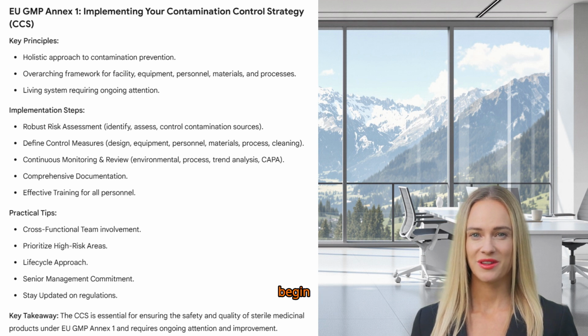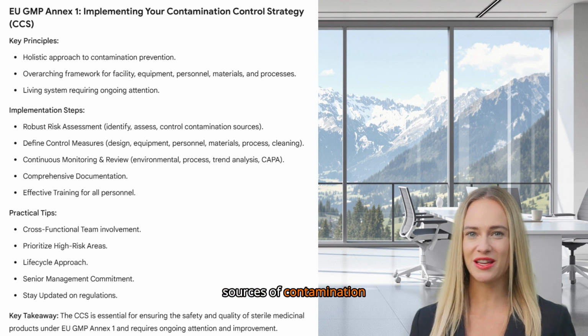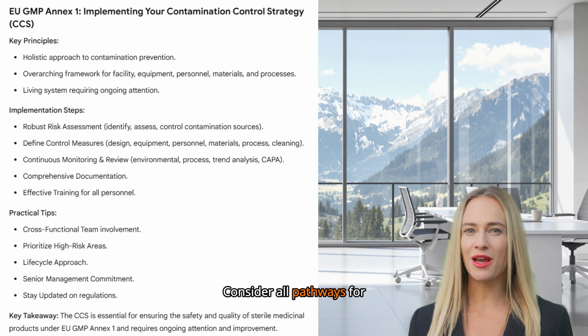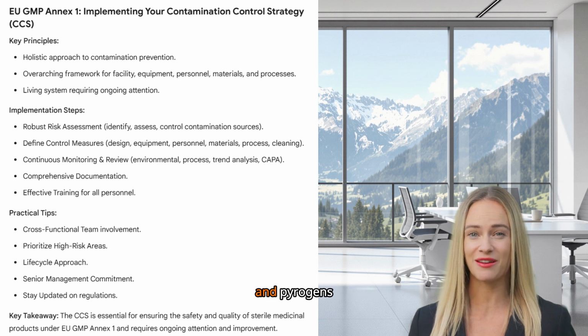So, where do you begin? The foundation of any effective CCS is a robust risk assessment. This involves systematically identifying, assessing, and controlling potential sources of contamination. Consider all pathways for contamination ingress, including viable and non-viable particles, endotoxins, and pyrogens.